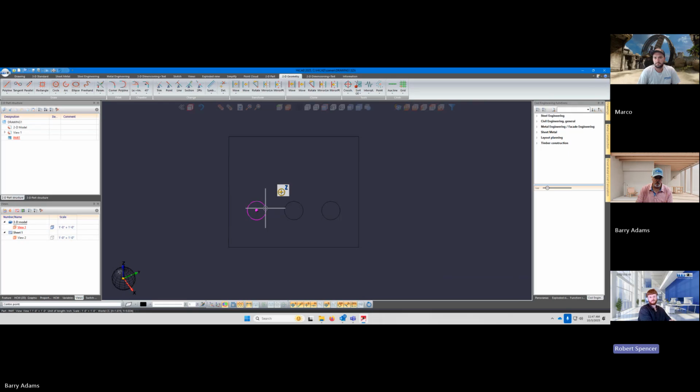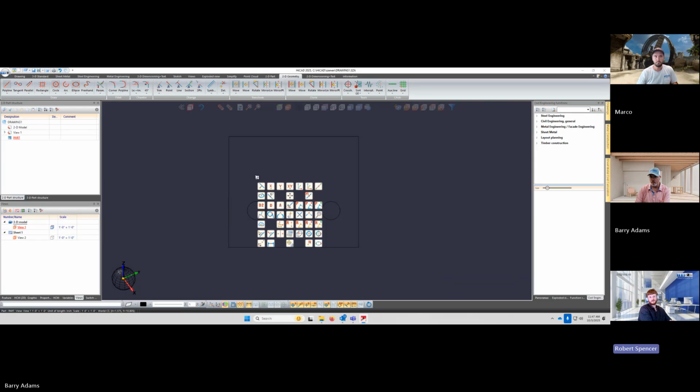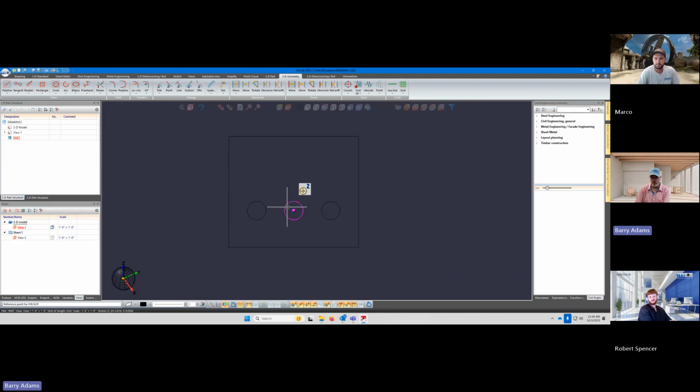You remember how to get there? It's either space bar or enter. Enter. Right now it's asking for a center point, but you can still hit enter. You can hit enter at almost any time inside a command. So remember, we have one here called from point. Yep, there it is.